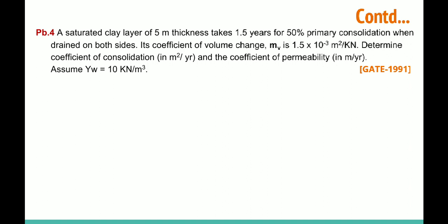So see, in GATE questions, whenever the unit weight of water is mentioned as 10, do not calculate using the 9.81 value. Your answer will be wrong. In the question it is mentioned to take 10, so we have to take 10. Okay, so now let us go for the calculation.